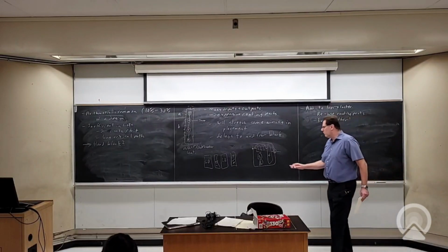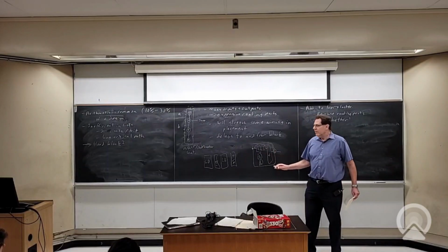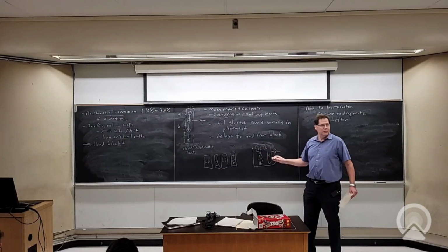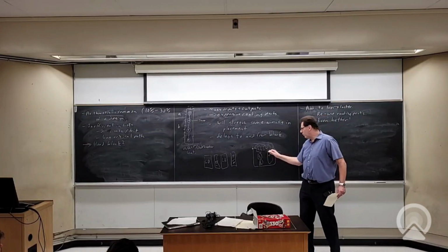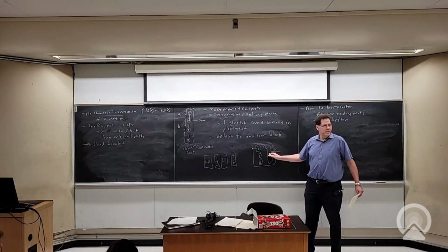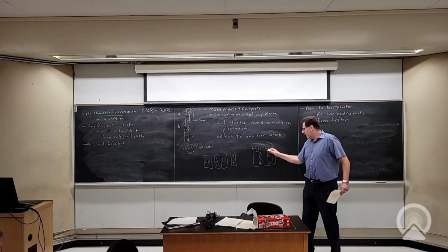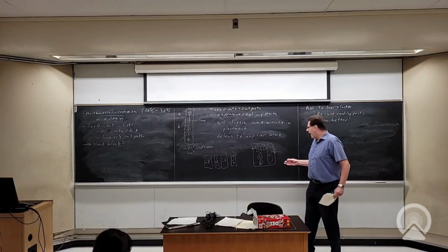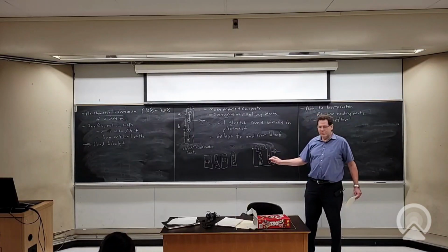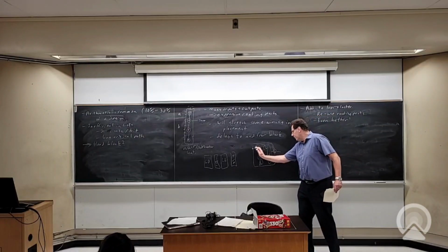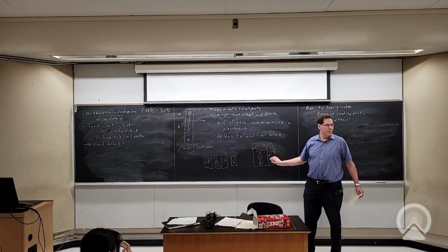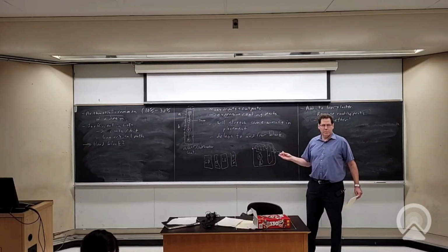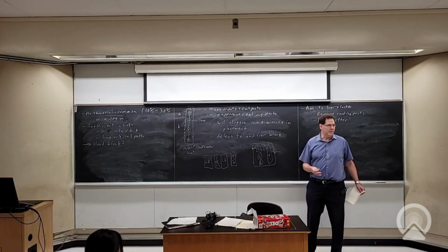Instead of saying use the LUTs or use the adder, you can say, well, why don't I cascade them? Why don't I just say that I will always go through the LUTs to get to the adder? Because often I have logic in front of my addition. So I can make use of the LUTs and the adder at the same time, as long as you wanted to do something before the adder. If you didn't want to do anything before the adder, then you could just program the LUT to be a pass-through.